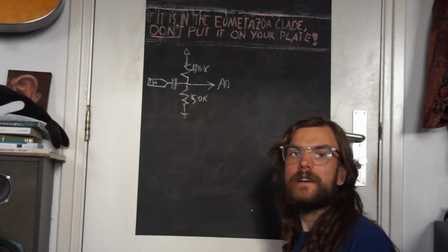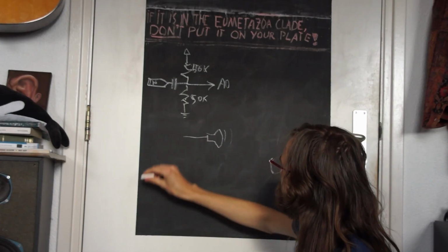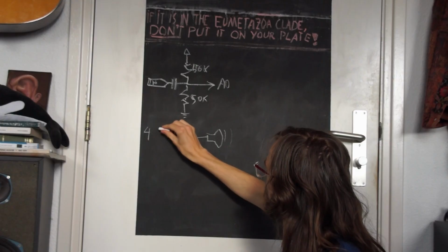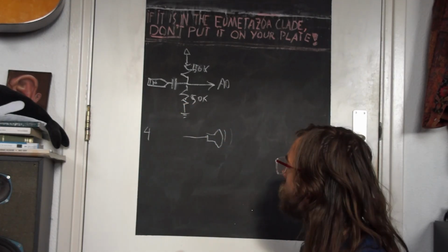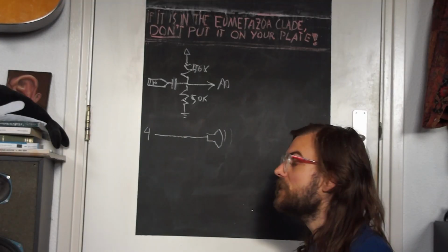Our Arduino can only go between 0 and 5 volts on its output pins. We hooked up the speaker to pin number 4. And we told the Arduino to go to 0 volts if our guitar signal is on the lower side and to 5 volts if it's on the higher side.